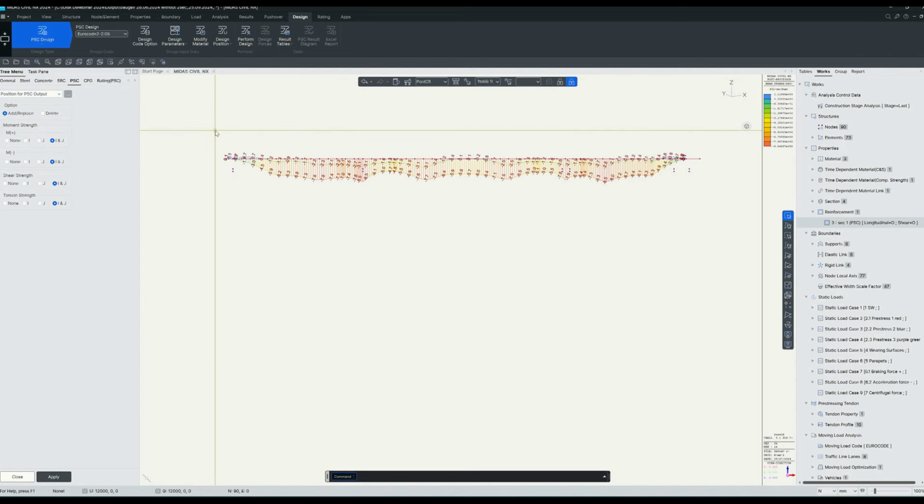If you want the report about one particular or a few particular elements from the model, you can ask MIDAS to create it in an Excel file by choosing a few elements. If you choose all the beam, it will take too much time, so don't do this. Click Apply.